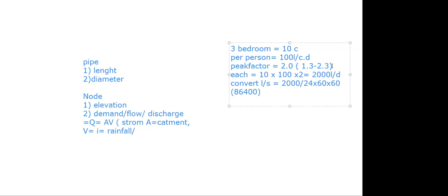And at the end of the day, you're going to get 0.023 liters per second. So in front of every house, if you use your pump and you measure the flow of water in front of your 2-bedroom apartment that is expected to contain 10 persons. Remember, it could be a duplex that can contain 10 persons. It could be a 2-story building that can contain 10 persons. It can increase to 20 persons. But it's an assumption. You must make reasonable assumptions as a consultant.